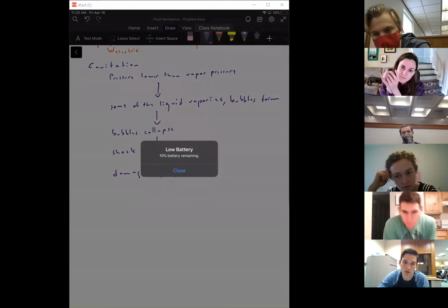All right. So the pressure will be lowest going into the pump. And remember, we also said that if there's cavitation anywhere in the pipeline, it will be in this pipe before it gets to the pump. But the pressure can also get lower at some point inside of the pump. So if the pressure going into the pump is too low, and it drops any lower when it's inside the pump, then there will be cavitation and the pump will be damaged.